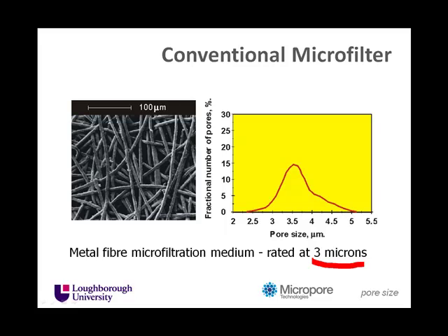If you were doing microfiltration, then you could easily capture particles of this size inside the matrix of the filter. So it's not really a surface filtration, although sadly we talk about these things as being a 3 micron pore size filter, and that kind of implies sieve. Reality is the microfilter isn't a sieve.